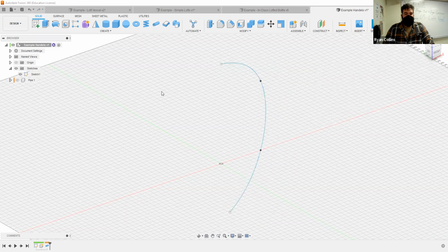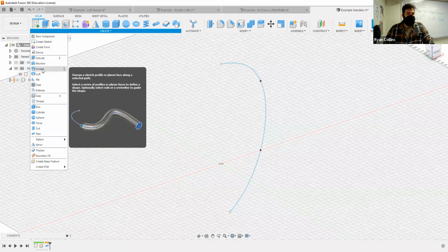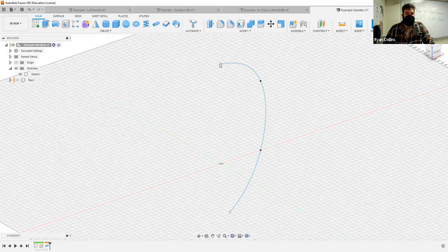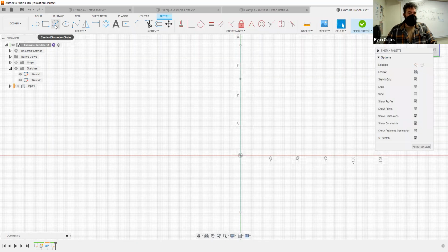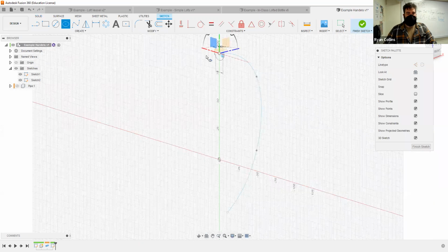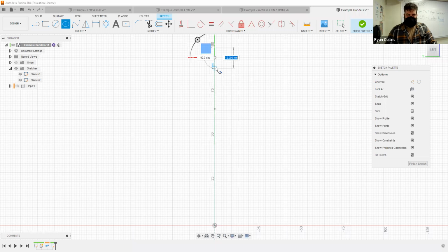Open up the sketch again. Next one up is a sweep. Now, a sweep is the same thing, only you create your own profile. And to do that, it needs to be a profile along this plane. So let's create a sketch facing that line. And let's say, I don't know, let's make it an ellipse. I selected right on the end point there because I started it there. Ellipses sometimes do some weird things with their selection process.